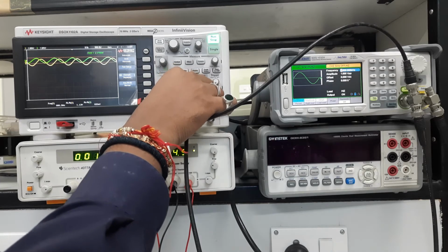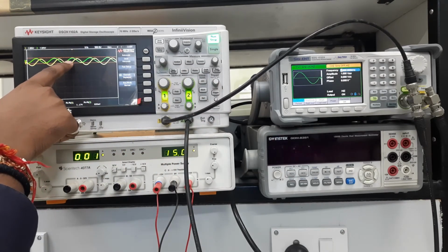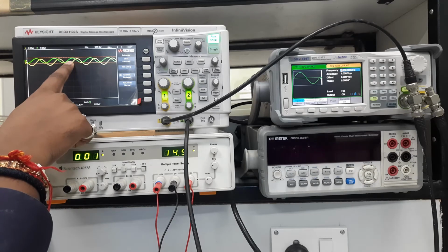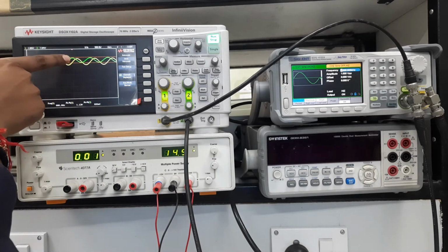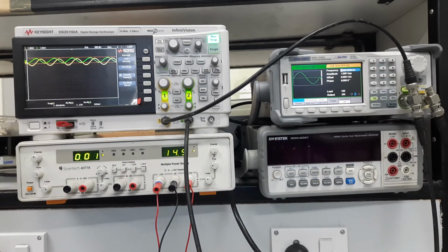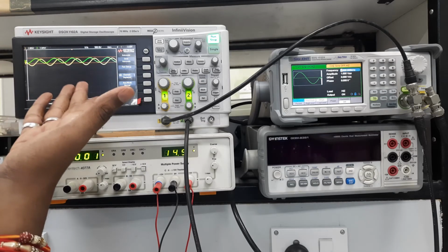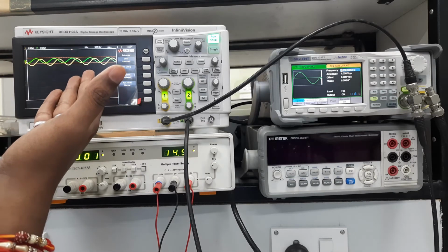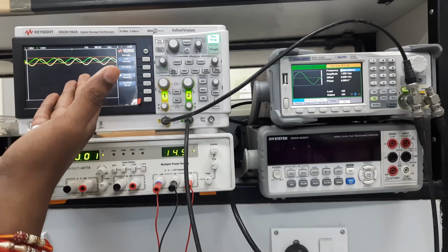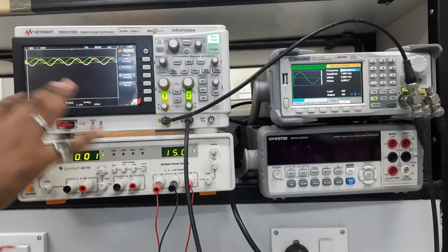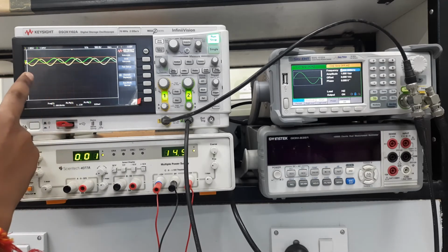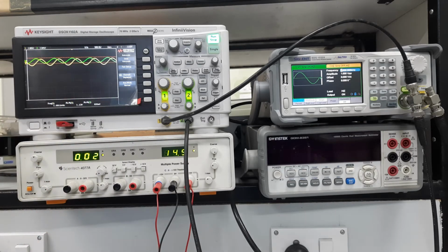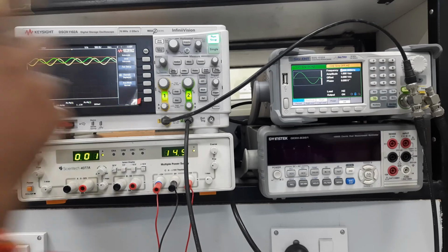here you can see this is the 0 reference of the input. Here is the 0, but we are getting the maximum. So there is a 90 degree phase difference between the input and the output signal. Obviously, if you integrate the sine, we will get the cosine, right? So that is what we are getting. Actually minus of minus becomes plus, right? So we are getting plus here at the output. So this is the sine.